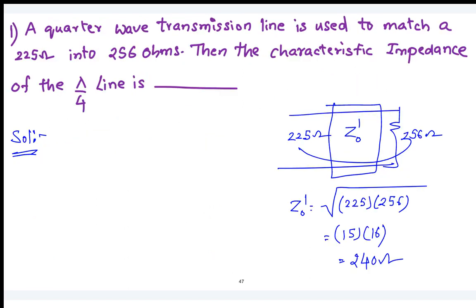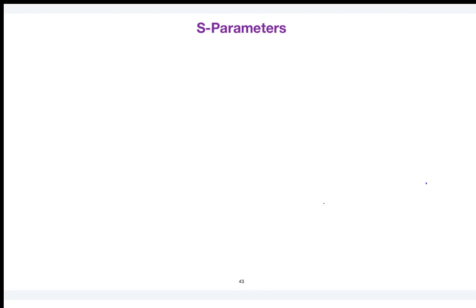So first I will give the properties of the S parameters. Anyhow, you are going to study this in microwave, so I will just tell a few simple points. If it is a reciprocal network, your original S matrix has to be equal to the transpose of that matrix. Will you agree with me? Just now, even in the problem, you have seen S12 is equal to S21, which means that even if you interchange the elements, your transpose matrix is going to be the same. Suppose the S matrix is a 3 by 3 matrix, instead of verifying all the elements, you just take the transpose of the matrix. If the transpose of the matrix is the same as your original matrix, then the network is said to be reciprocal.